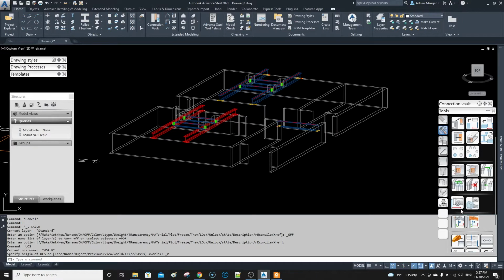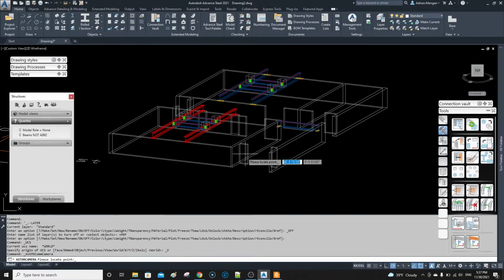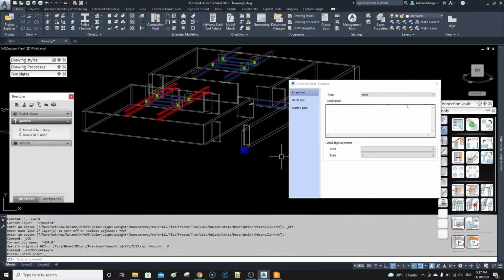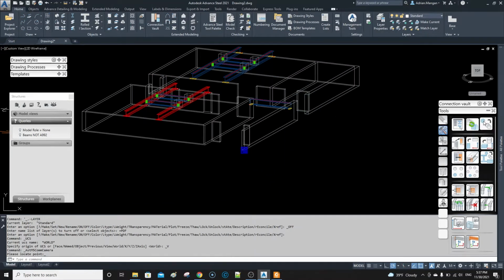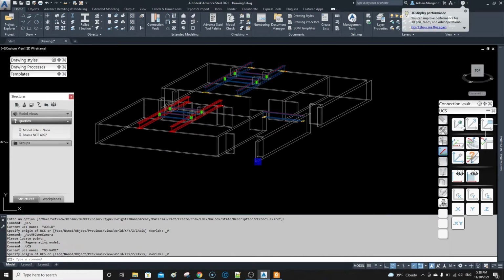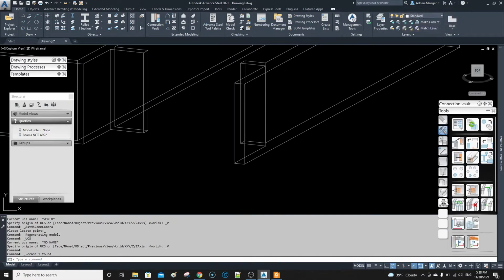I'm just going to set a camera in here at this view I'm looking at. So I'm looking in this way, so I have gone up here and I've set to look in through the UCS. So just go to where you want to look from and then hit this one here, and I'll delete that, and then we'll go back and put in a camera.